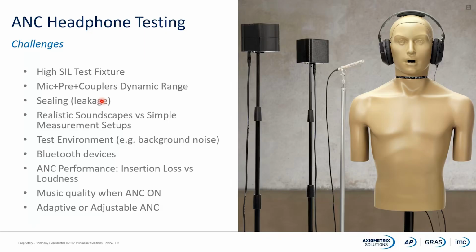The test environment, and particularly the background noise, is important to measure. If we have high background noise, that will affect the reliability of our measurements. Wireless devices, such as Bluetooth devices, will require an analyzer that has the possibility of communicating directly with the device with a Bluetooth interface. So this is something that should be considered.